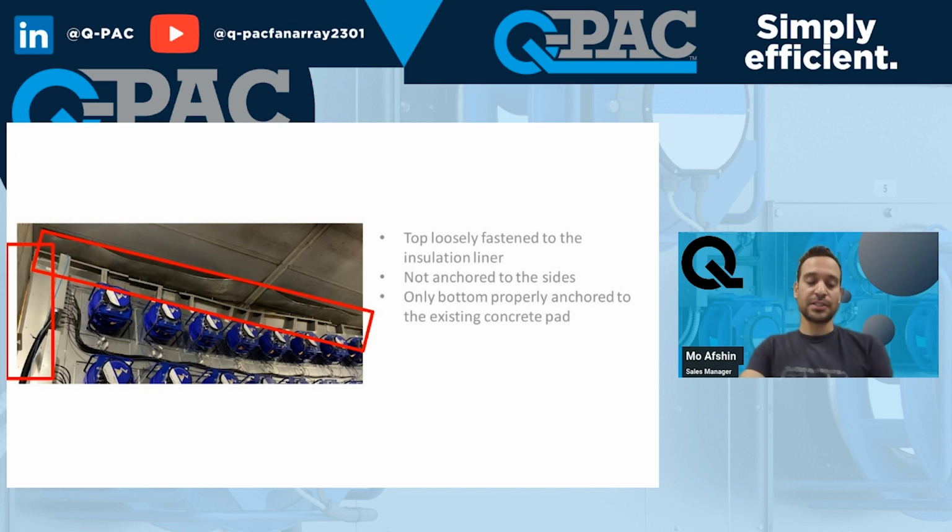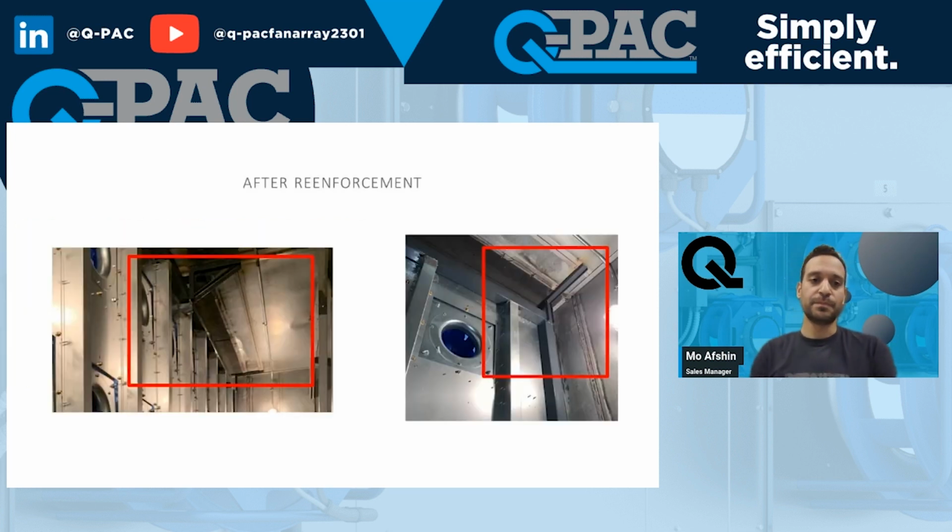Fortunately, our bulkheads are designed to handle a large pressure differential, so the bulkhead really had no problem here, and they just had to put in some reinforcement. As you see, they put some 4x4 structural beams on either side, and they also put some reinforcement at the top. And then they ran it. This system was at 8 inches of pressure differential. On a very large bulkhead, the pressure times the area gives the force, so that force can be very large.